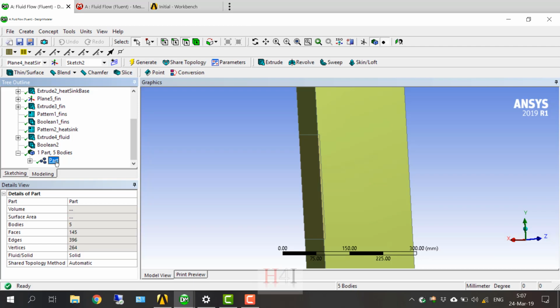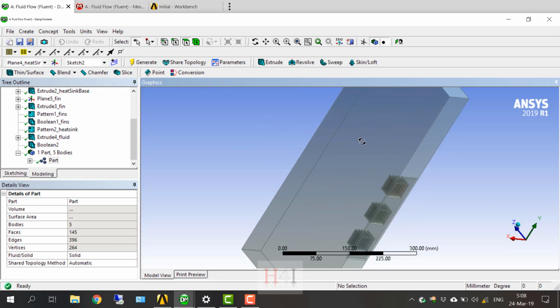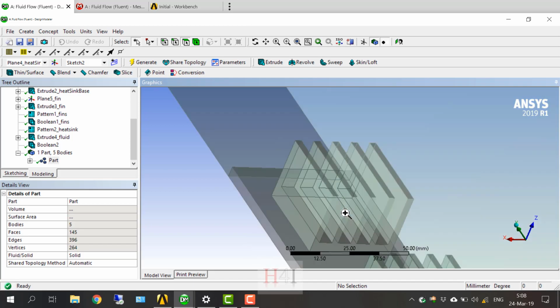When the body is complicated, like in this case, where we have fluid domain and solid domain, it is very complicated and hard for the mesher to create a mesh in the fluid domain which connects with the mesh in the solid domain. You will find it very hard to achieve this in a good way. You can create a tetrahedron mesh or mesh in a rectangular way, but it will not be efficient. So we need to overcome this challenge to create a good mesh with a low number of elements, and at the same time the mesh at these surfaces must be connected.